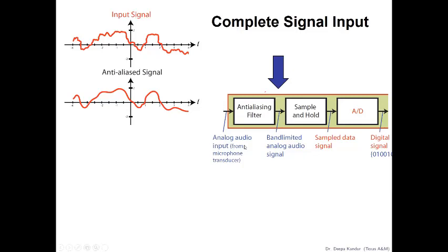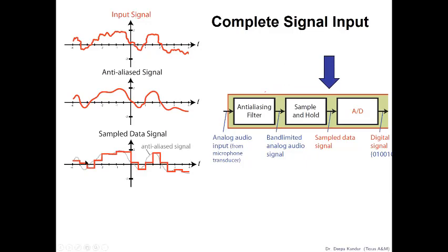Now, practically, an analog to digital converter that's going to take that signal and digitize it, we can break that up into a couple of different actual operations that have to go on inside that device. The first of which usually is some sort of sample and hold circuit, meaning we're going to have to grab the sample value from our original signal, so it's varying in time, but my A to D converter cannot work instantaneously.